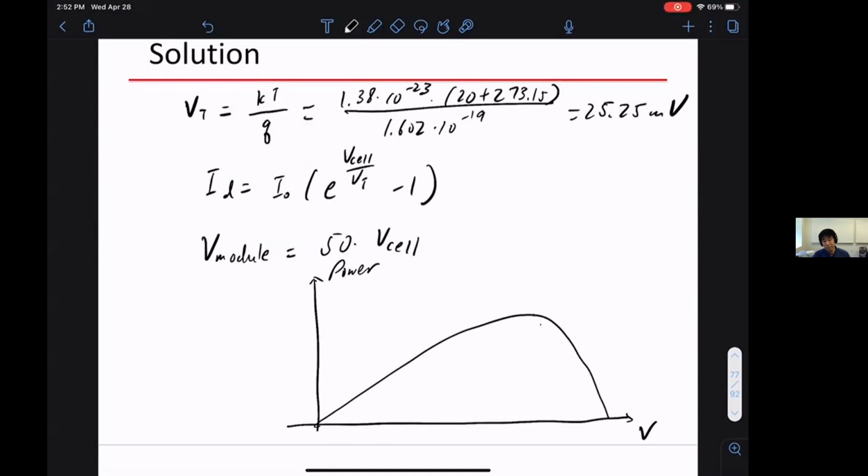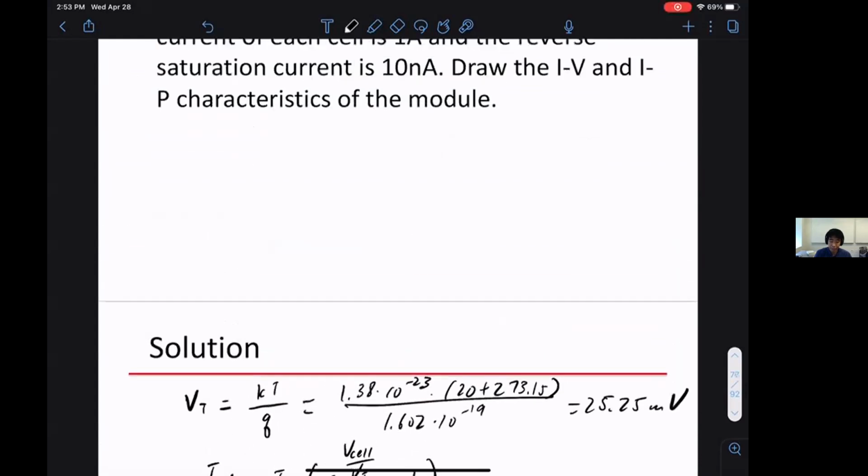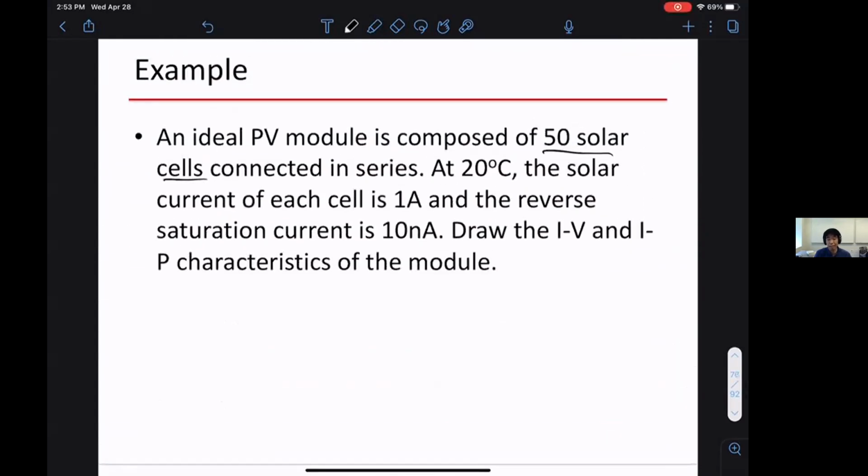So a series connection boosts the voltage, and if you have a load that operates at say 20 volts, then it's better for the load to connect things in series and just boost the voltage that way. But then of course you have to make sure that in practice, not all of them will see 20 degrees Celsius temperature, right? Each cell will see a slightly different temperature at least. Then you have to worry about how you balance the current. How do you make sure that you're drawing the same amount of current out of each cell? Again, we actually design this. There are some feedback mechanisms that make sure the currents are correct in this situation.